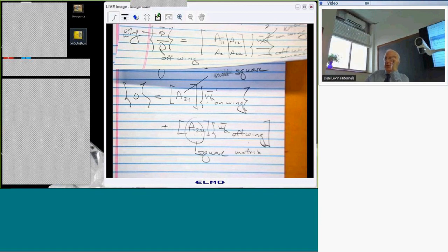But they're really there. So when you run the code and plot the pressure distribution, you'll see these singularities, or near singularities, appearing. Of course, if you're doing boxes of finite dimension, you're never right at the leading edge. You're always at least half a box length away from the leading edge, so you never really get there. In fact, you don't want to go there numerically because you'll get in trouble. Which tells you that you want the boxes small enough to get a good answer, but not so small that you get a problem with the singularity at the leading edge.